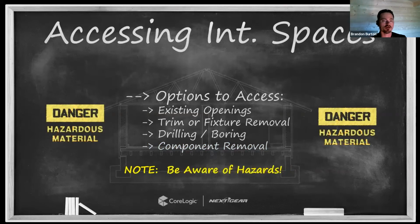Electrical safety is one of them. The other is hazardous materials that may be present. As soon as I start disturbing assemblies, I need to understand the likelihood that something like lead or asbestos will be present. I also need to understand the laws and regulations locally, right? Understand your state requirements as they relate to disturbing a wall assembly, regardless of the age of the building. For example, I live in Washington State, and in Washington State, it doesn't really matter how old the building is. If I'm going to start disturbing a bunch of drywall, then the asbestos regs kick in, and the age of the building really has no play in that. So just understand what your local laws and regulations look like.